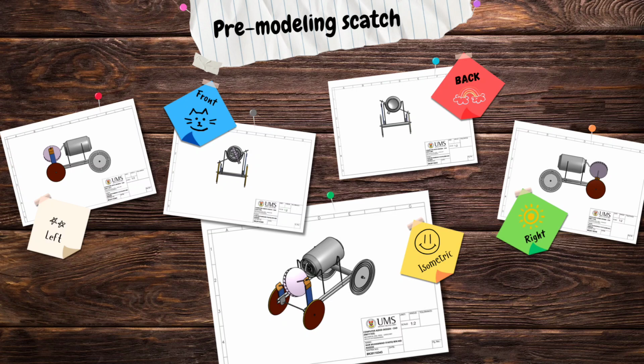We plan to design our car as flat as possible so our car can move easily. Due to this strategy, we heat the boiler outside the engine instead of including it inside the system. Additionally, we also plan to apply a forward wheel drive system, or FWD, to create a pulling effect in the car. This is because pulling creates less friction than pushing.